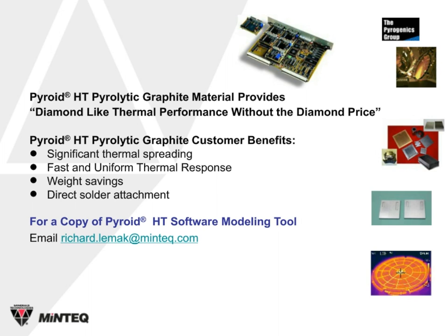The types of metallized coatings that are available is a variety, and not only the metal itself, but also the nature in which the coating process is performed. Among the coatings that we have explored either ourselves or with customers would be a titanium, followed by a nickel chrome, followed by a gold layer, or titanium, followed by nickel, followed by gold, or titanium platinum gold.